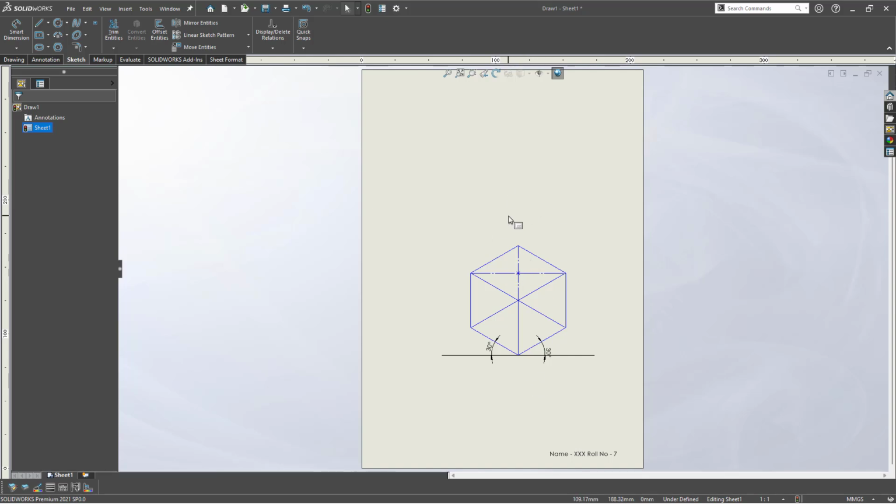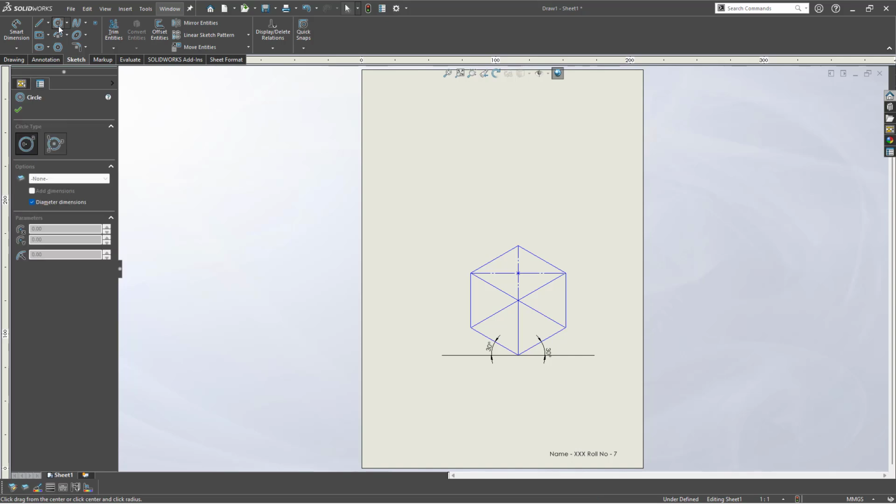Now I need a sphere on it, which should be placed. A very important factor is the sphere, the circle. If you take the sphere, or the hemisphere, or the circle, whatever it is, in the isometric view it should also look the same. This sphere as well as the hemisphere should have the same radius and same diameter in all the views: the front view, right view, isometric view, whatever the views, it should be the same dimension. That you should remember. Okay. Now even in isometric view, the true value of the sphere is diameter 50. Correct.